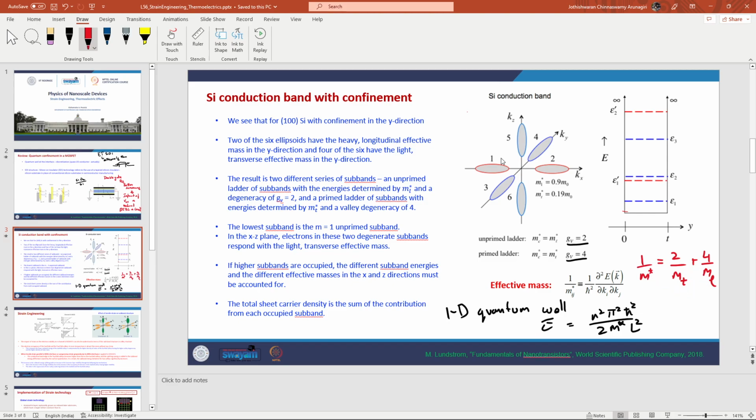So the introduction of strain of this kind in this material has reduced the combined effective mass of our electron, and due to that low electron effective mass, the mobility of the electrons also increases. So ultimately, when we are talking about quantum confinement or strain engineering, the basic idea is to change the internal energy level configuration for our channel, and through that we will achieve some kind of mobility enhancement. There are also other benefits for this.